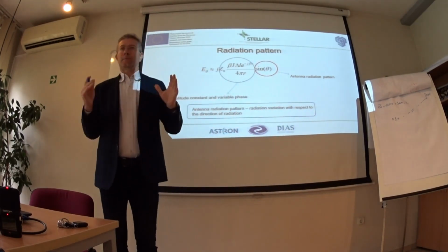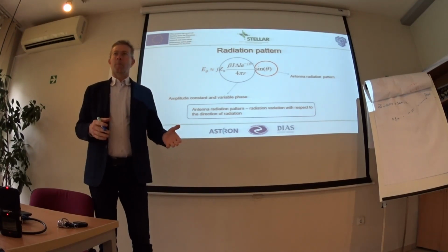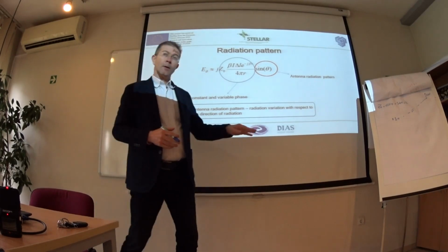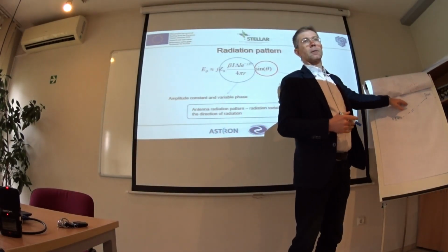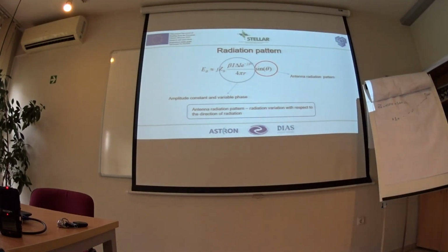In a lot of places in electromagnetism or antennas, the dimension is ohms, but this is not a resistance, not a conductor property. It's simply a relation between E vector and H vector. Because E vector is volts per meter and H vector is amperes per meter, it gives us volts over amperes, which is usually denoted as ohms.